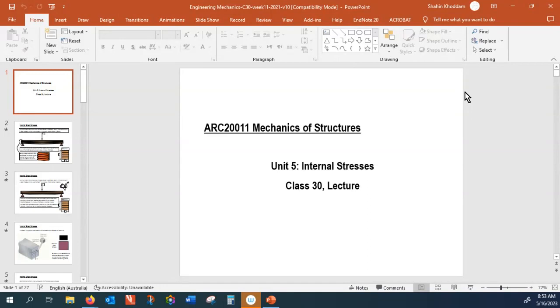So it is not only a function of force and area, but also the orientation of the area. You could make it such that the area is perpendicular to the force. That becomes normal stress. So you can think of the stress at a point; depending on how you evaluate it, what your coordinate system is, the stresses would be different.